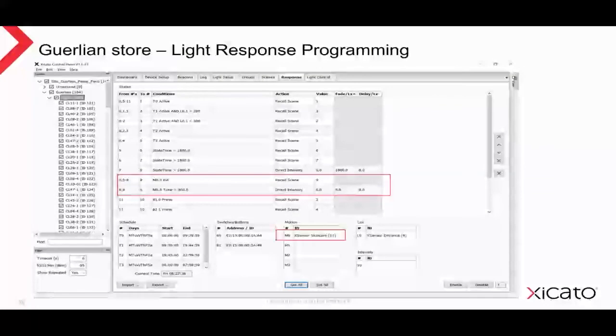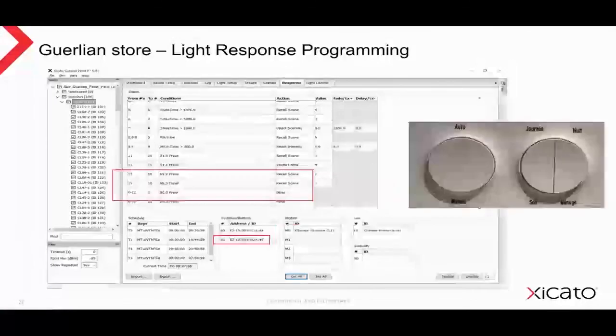Once we are into the light out time zone, we then switch to a sensor input and recall the delivery scene when the motion is detected. At this point, some light come up and remain on until 50 minutes after the last motion detection event, thereby ensuring the lights remain only on until after people have left the shop. And finally, the last piece of this control scenario, we add a manual control override, which can be seen here.